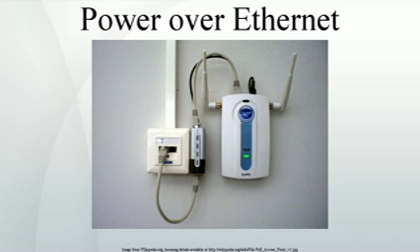In Mode A, pins 1 and 2, pair number 2 in T568B wiring, form one side of the 48 VDC, and pins 3 and 6, pair number 3 in T568B, form the other side. These are the same two pairs used for data transmission in 10BASE-T and 100BASE-TX, allowing the provision of both power and data over only two pairs in such networks. The free polarity allows PoE to accommodate for crossover cables, patch cables and auto MDIX.